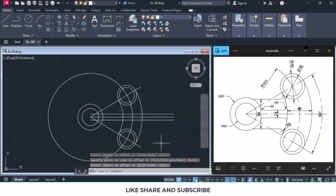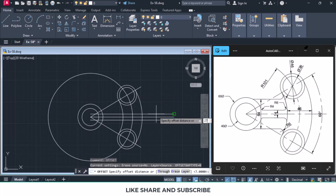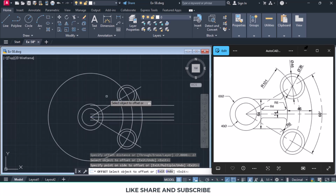We press enter. Now we want to draw these two lines. So we'll offset the upper line at 27 and lower line at 27. So again offset and we give the distance as 27. Select the object to offset, side to offset, object to offset, and side to offset. Press enter. So this total distance is 54.